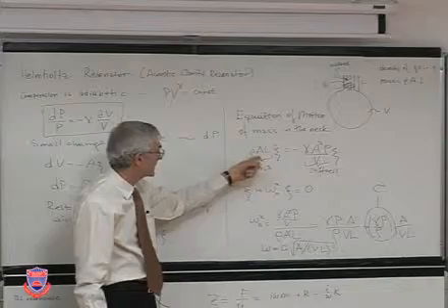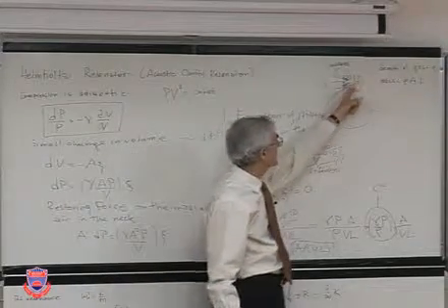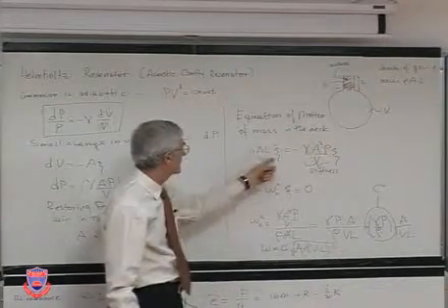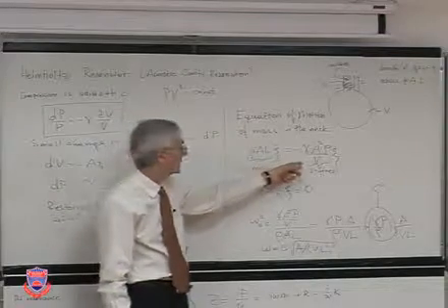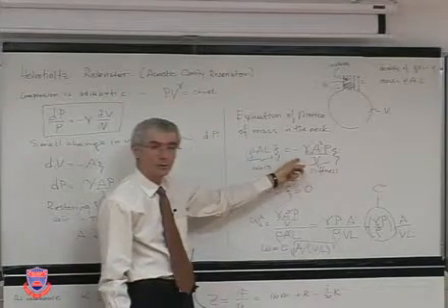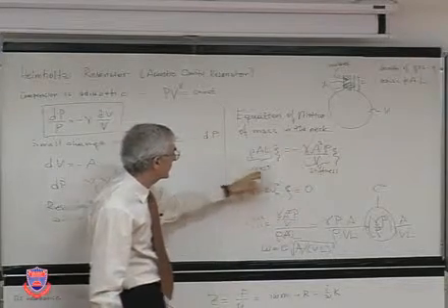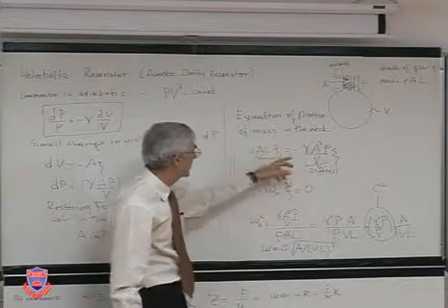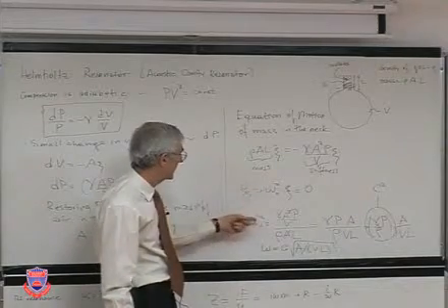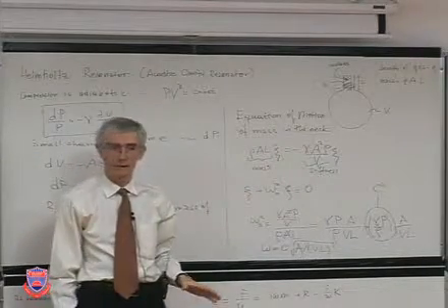Well, the mass itself is density times A times L, and its acceleration. And the restoring force we have already just found. Then what we do have is stiffness divided by the coefficients. When you divide them, it gives you the natural frequency of the system.